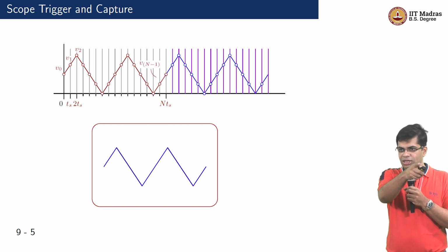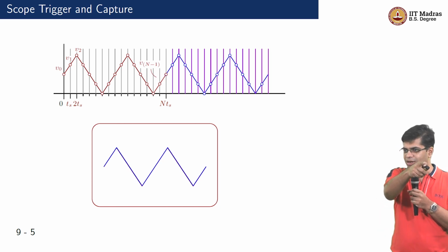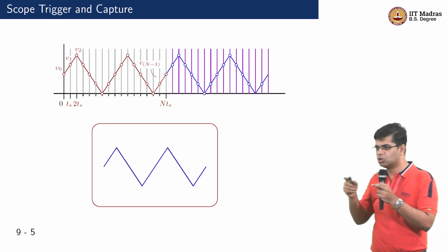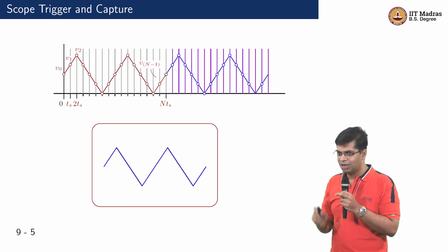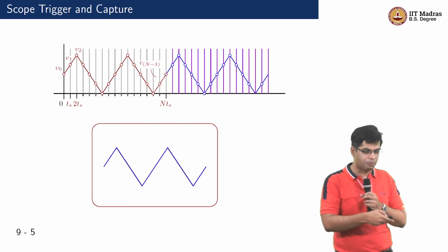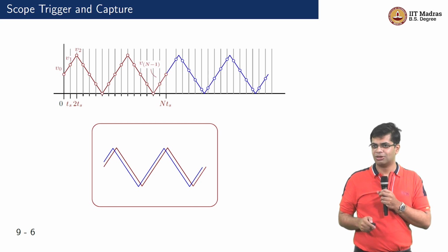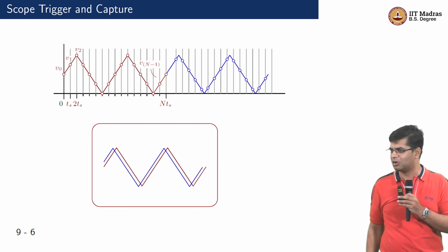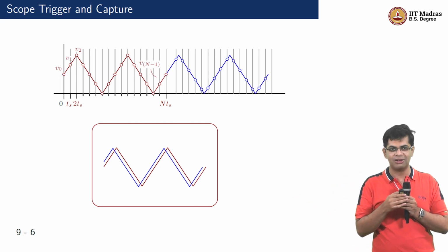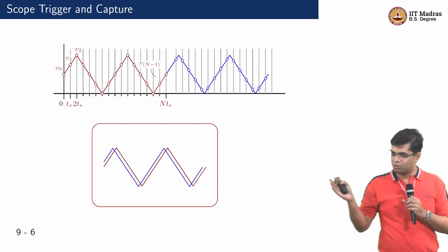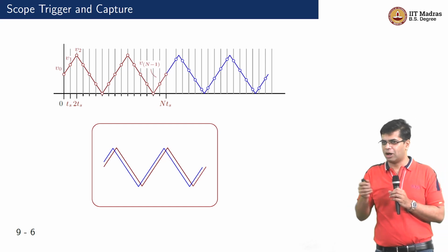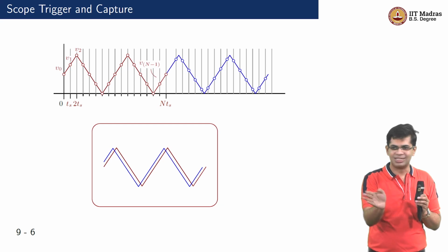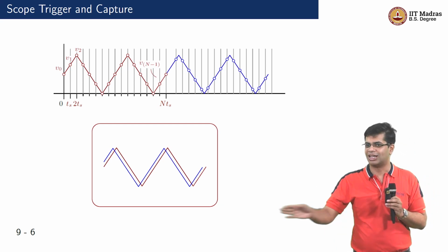And so you see the waveform, I've changed the color and it's not that evident. Just changed from maroon to blue, but they have just overlaid so you don't see it move around. Now you see what happens if you don't trigger properly. Suppose you went to sleep for some time and then started the measurement of the next 200 points. What would happen? Your waveform has got shifted. So every 200 points, if you have this little bit of laziness in starting, your waveform will dance around.